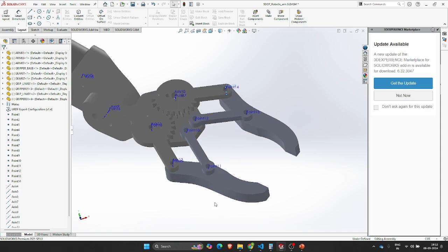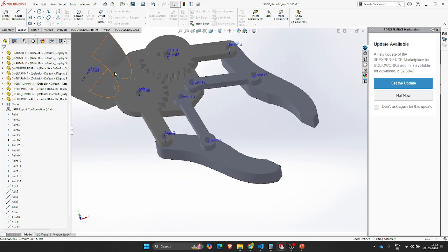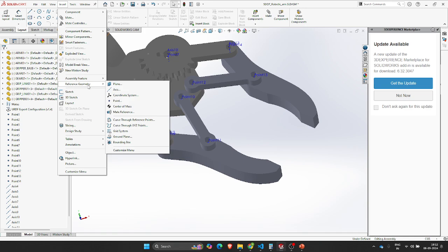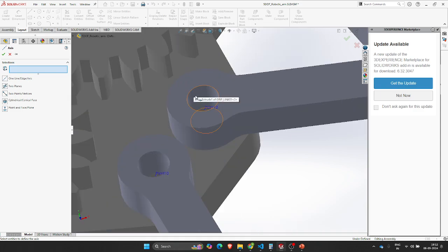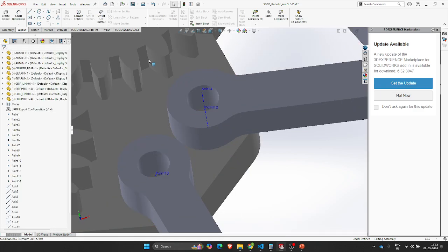It might be a revolute joint or prismatic or anything. It's up to you. We will define whether these joints are revolute or prismatic in the SolidWorks to URDF converter. But before that, we have to create all these steps. So I'm repeating the same thing I repeated that time, but that's important to understand.